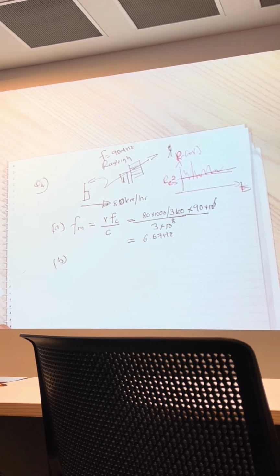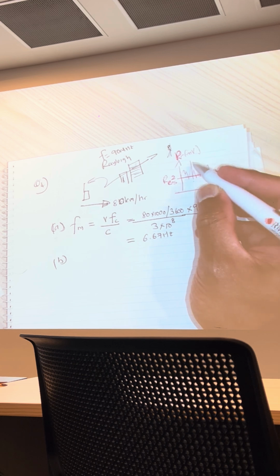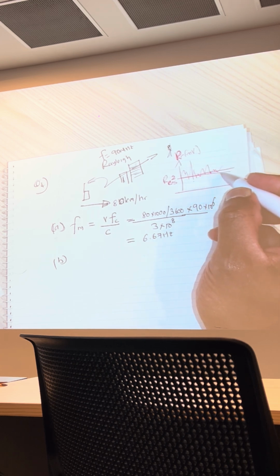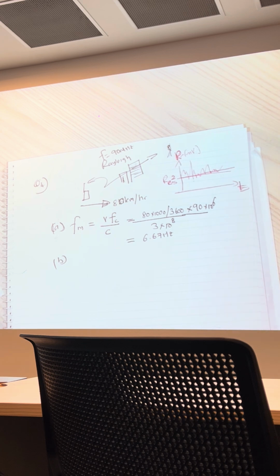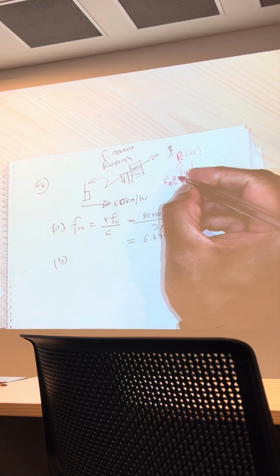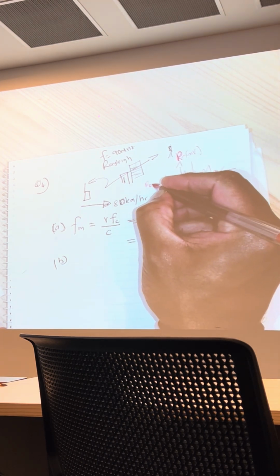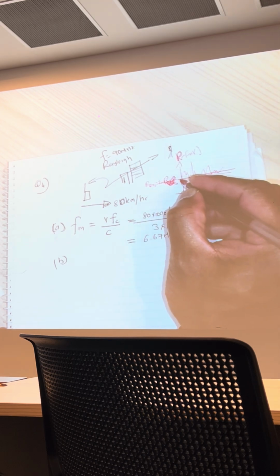Part B. Find the level crossing rate NR for the signal to go below an amplitude of 0.1 millivolts. So if you look at this diagram here, this is a received signal, right? This is how I've drawn the received signal. That's the RMS, so that's 2 millivolts here. RMS equals 2.